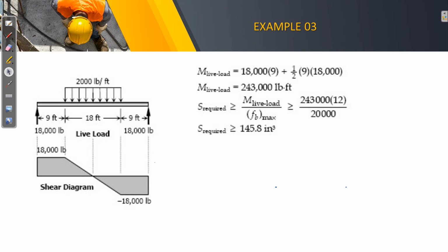So of course, we cannot use the general formula for obtaining the maximum moment for a simply supported beam. So this is no longer the simple case. Simply supported, but your loading is not distributed all over the entire length. So therefore, you still need to go over with the shear and moment diagram. And of course, your criteria, the maximum moment, is the area of the shear diagram. Okay,